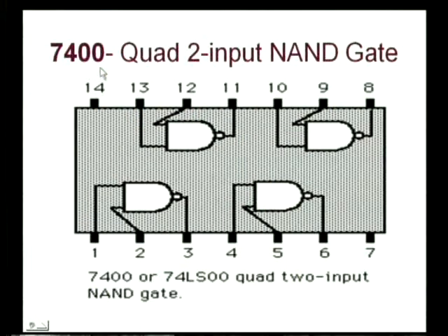When we move into the laboratory, we should be in a position to work with these gates. For this, we shall get familiarized with the various ICs used in the laboratory that contain these basic gates as well as the NAND and NOR gates. The first gate that we shall see is the 7400 TTL gate. This is a quad 2 input NAND gate.